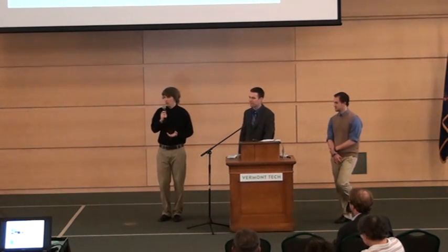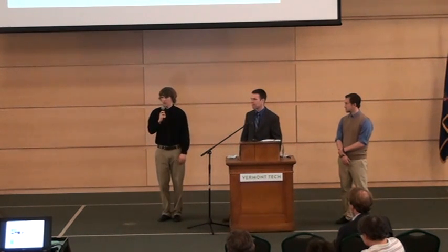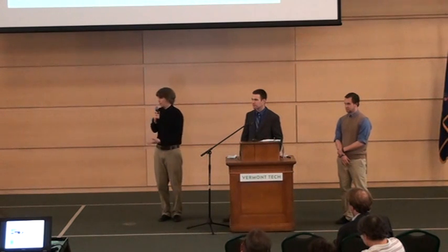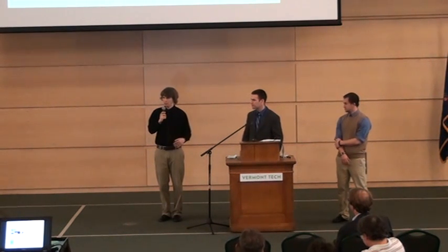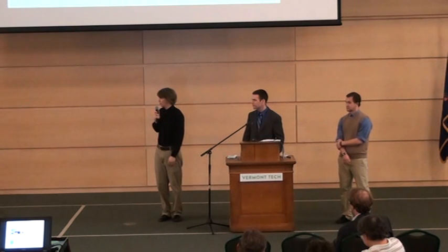The motor would shut off, so it wouldn't be testing anyway. But one thing you could do if you were worried about that, the Arduino could run off a 5-volt supply, and you wouldn't have to have the computer running to get the cycle count, but you wouldn't get any data from the cables. So if you absolutely had to run a test where you weren't taking data in from the cables, you just wanted to flex it for a long time and see if any broke, you could run it with the computer off, and the Arduino would keep track of how many times it cycled.